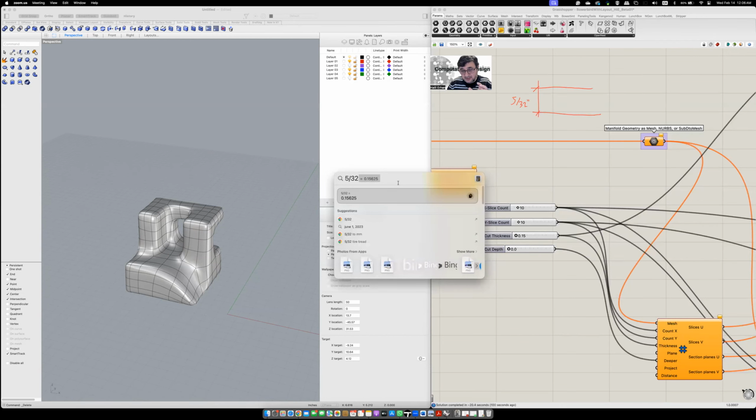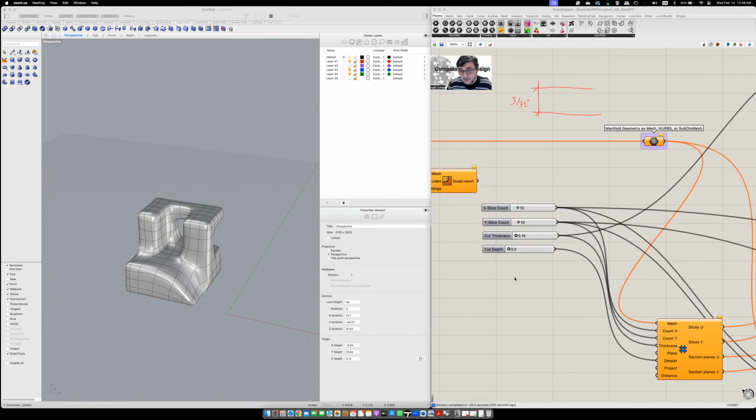When the laser cuts it, it makes the cut a little bit bigger. So when the slices get attached together, if you don't want them loose, we want them a little bit tighter. That's why 0.15 is going to work for us. So adjust this thickness to 0.15. Why are there more options? Because you may work with plywood, fiberglass, plexiglass or other material, and depending on the material thickness, you adjust this.